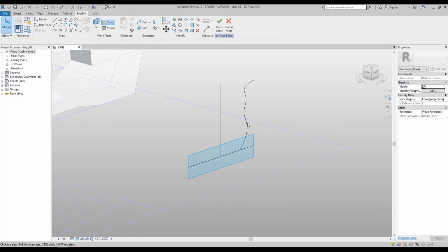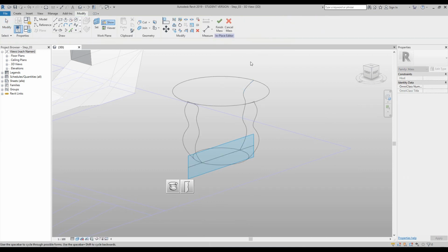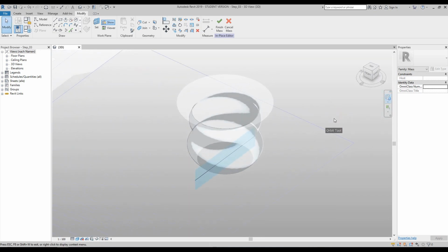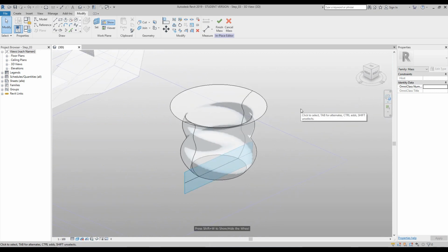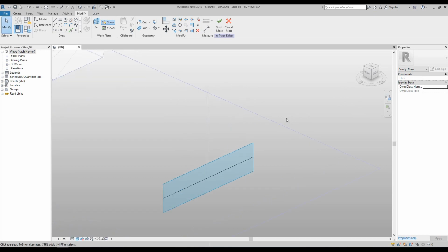And then to do a revolve form, you need to make sure that all lines and splines are selected, as well as the revolve central pivot here. So with the Control key, select it, and then go up to Create Form and press Solid Form. Now you'll notice you have two little buttons that have now arrived on your screen, so you can create an individual face, or you can create the revolve sweep, to create something that looks like a bit of a vase or a jug. I want you to delete this, so Control Z, until that spline line has disappeared.